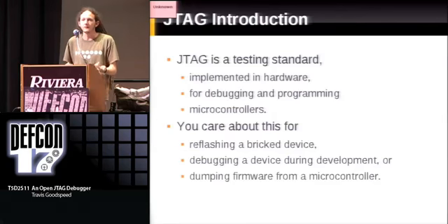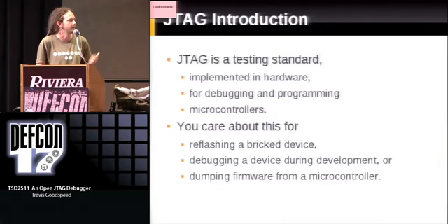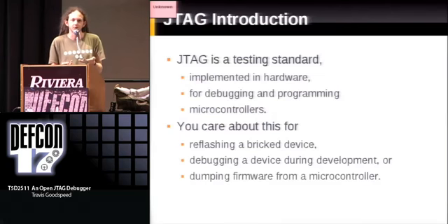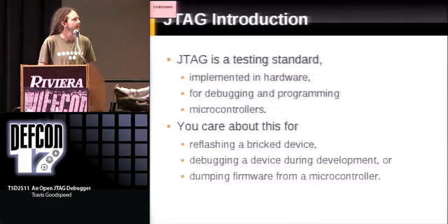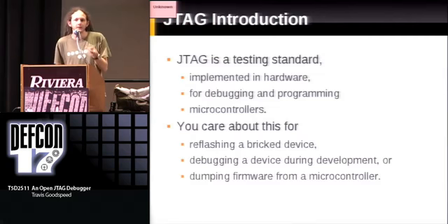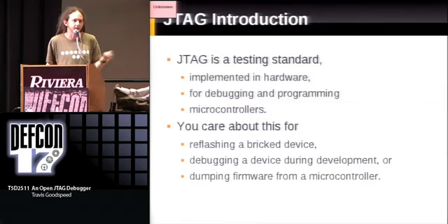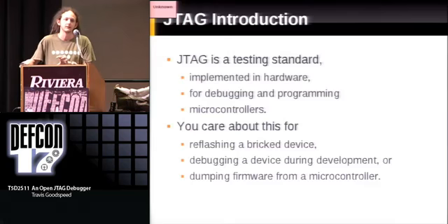So you can use this to program a device, to read the programming out of it. If you purchase a device, you can dump its firmware and then begin to analyze it and look for problems. Or you can clone it. You can manufacture your own unit with similar hardware and then flash the original software into it. And the access control mechanisms of this are only intended to prevent that. They don't really care that you might be able to debug. They don't really care that you might be able to view RAM. All they worry about is that you might be able to copy the contents of flash memory into another chip and then execute that or sell it, making a counterfeit product.